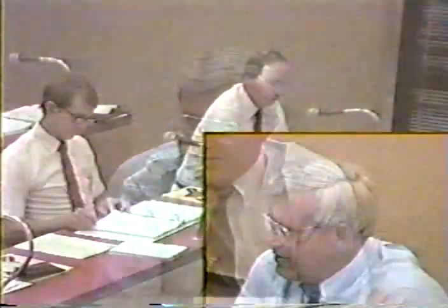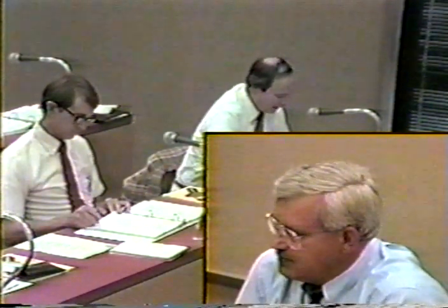Well, that's the reason I showed the example where we used the berm with material on the top of it, and that adds a lot of mass or weight over the shear key. So that's a good point. Excellent point there. You need something to increase the amount of weight on the shear key to give it strength. That's one reason I'm going in this scenario, starting with one and going to the other. It's a very logical sequence, I think. And those are excellent points.